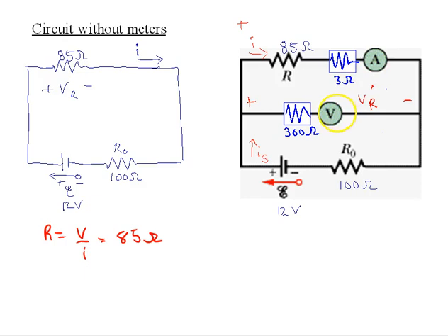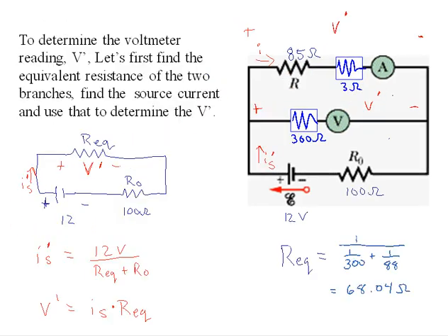And how we chose to measure the voltage across the resistor, we're measuring it also across the ammeter. We could have set this up so we measured with the other side of our voltmeter here instead of here, and that would give us a different voltage. So how we measure our circuit does affect what measurement we're going to get. So this is for you to do as a homework problem, but again, just what we're trying to find is your I prime and your V prime in our new circuit.